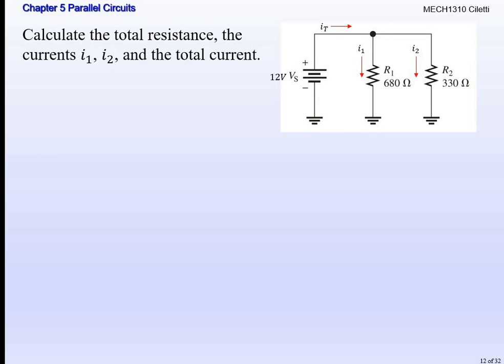We're going to do this circuit here. There are only two resistors in parallel now. See how they all go to ground? That's still a common node because ground is common. So you may not see the node above R1, but there is a node, right? That black circle is a node where circuits join together. Since they're all going to ground, we treat it just like a node because they're all going to the same connection. So these are in parallel.